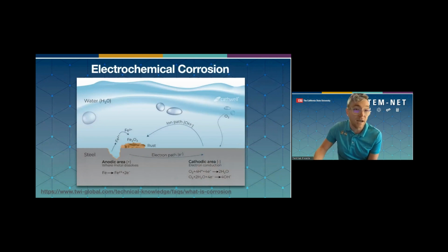And there's many types of metallic corrosion, but most are electrochemically driven. If we draw our attention to the figure I have on the screen right here, we notice the cathodic and the anodic regions. We have an electron path and the ionic path, which are propagated by an electrolyte. Again, this includes very humid air. Under these conditions, the anodic region begins oxidizing, leading to corrosion and metal loss.